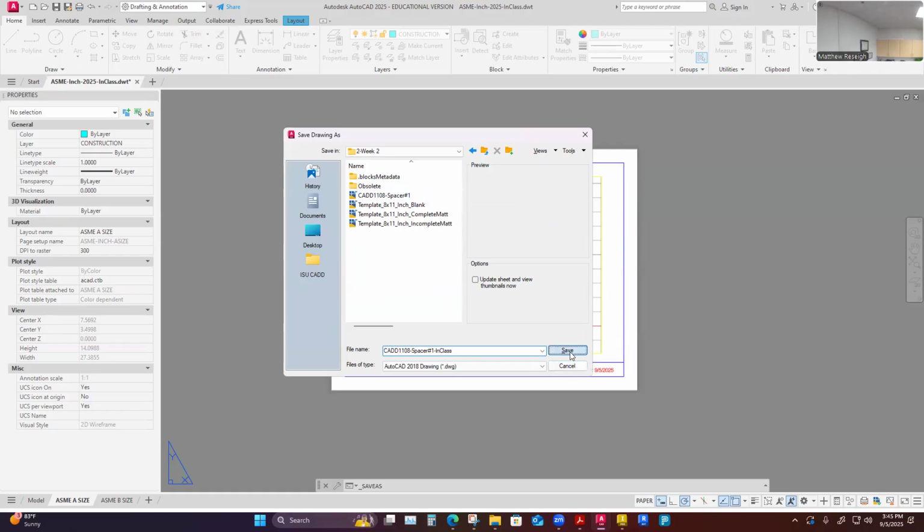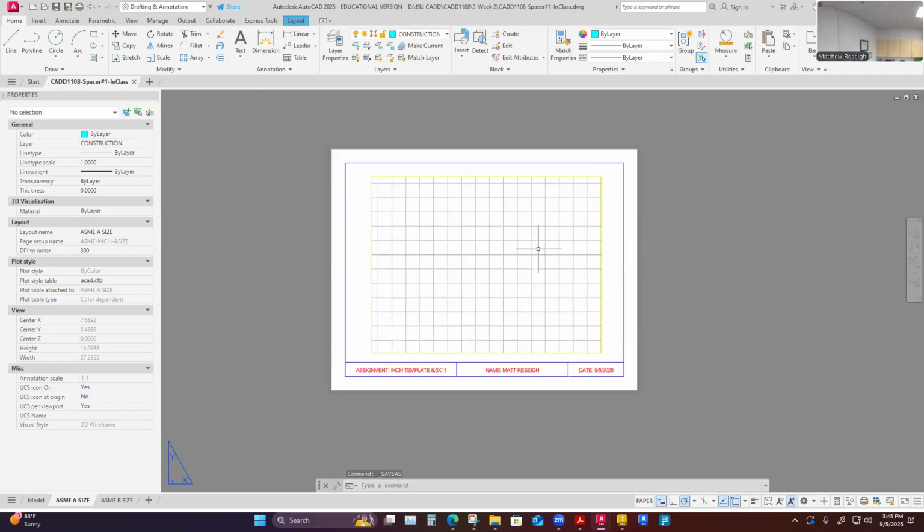In any case, the first thing I always do is protect my template, get away from it, and create a drawing. Already at the top, I've got the DWG as what I'm working from. It is my template file in all ways, but my template is now protected, and I have a DWG that I can go to town on and do all kinds of custom, specific things for this assignment. I don't really have to change anything in paper space at this point. I'm ready to actually go draw, so I'm going to go to model space.